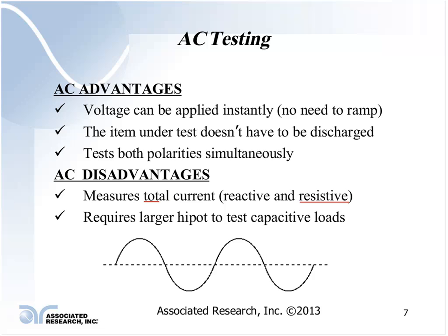Okay. In doing AC testing, it requires a Hipot tester that is larger in current capacity, because you have to worry about the distributed capacitance of the product. Everything that you test is a capacitor. You are testing the insulation between two current carrying conductors. That is a capacitor.